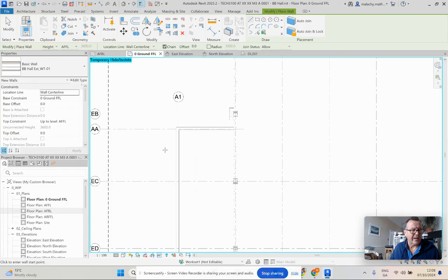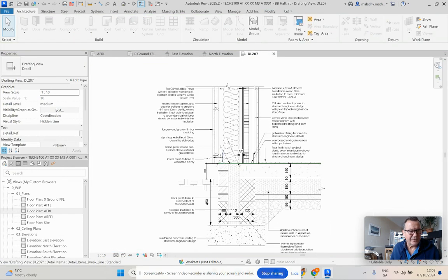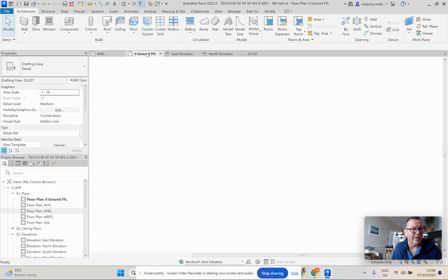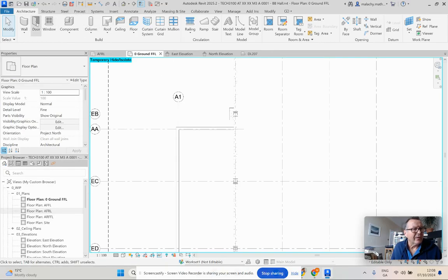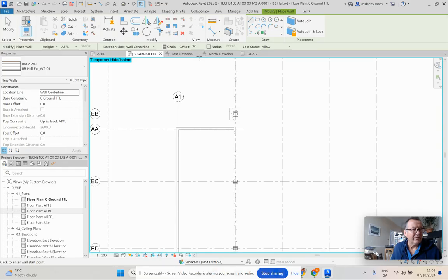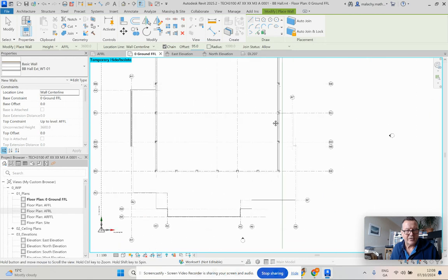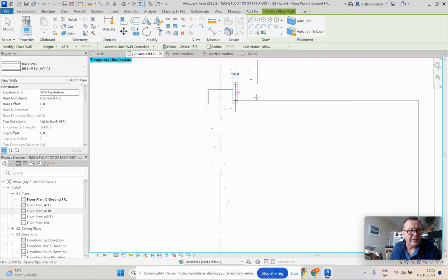Now, if you remember when we created the grids, I want my CLT wall to sit right down on top of my support load here on the foundation. The way I went about this is that I created the wall, I got a center point of that wall, and then as I'm drawing it, I'm going to do an offset of 95 from the center point. That's basically how I'm doing mine. Okay, so let's go back into here, to wall, and I'll do an offset in here of 95. All right, now I want to draw clockwise here, so I'm going to start at that point.